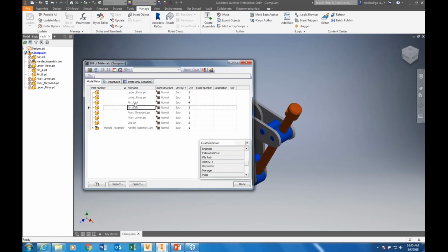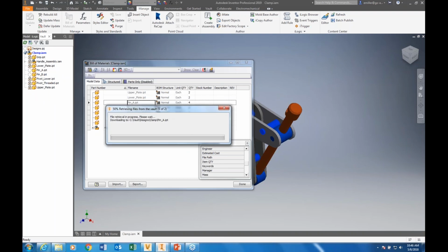So in order to change, we notice they're synchronized, so they're available for checkout because you see the white circle. They're not released, so they're work in progress, but I do need to check them out. So let's right-click here within the BOM manager, and obviously I like using the Vault browser for that too, so make sure you utilize that. And in this case, if I didn't have the Vault browser on, this is another way to see it and check them out. So we hit checkout there.